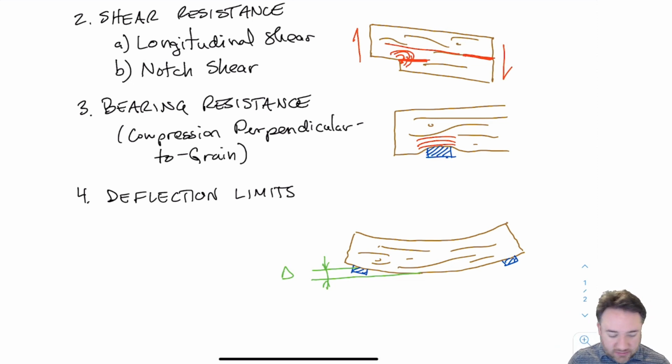And for a simply supported beam like the one that I'm showing here, we would want to check, for example, the maximum deflection of the beam. That might not be exactly at the center, depending on where the loading is. But we need to calculate that deflection to make sure that it's not excessive. Excessive deflections are a problem serviceability-wise, so we don't want people in our building to observe the beams visibly deflecting under load, because that would make everybody uncomfortable.